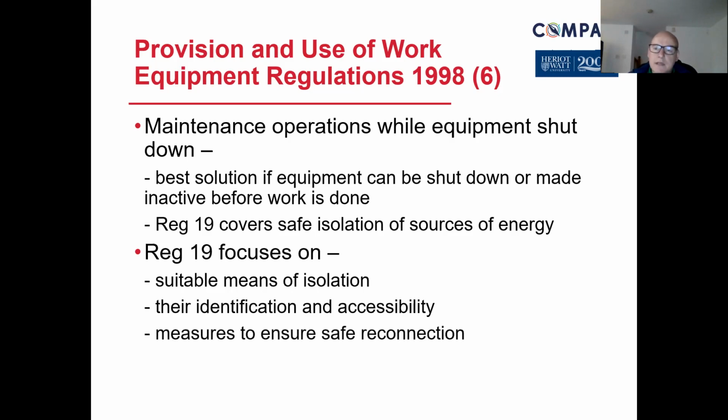Reconnection. So towards the end of the work, you're doing some preparatory work, and sometimes by that reconnection, it can partially energize or put some pneumatics in place that put pressure against a valve. It could be a variety of things. It could be electrical work, and while you've reconnected the electrical work, you've now created the full loop on the circuit, and therefore it's energized. So again, when we have reconnection, it's important that we think about what can happen, what could go wrong. And again, failure mode effect analysis is very useful in these areas to identify that.